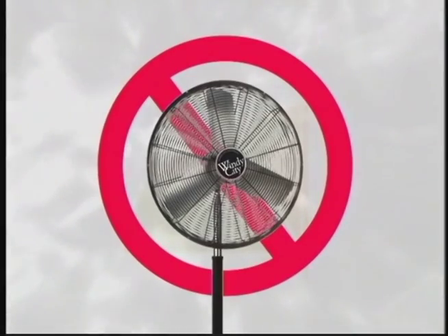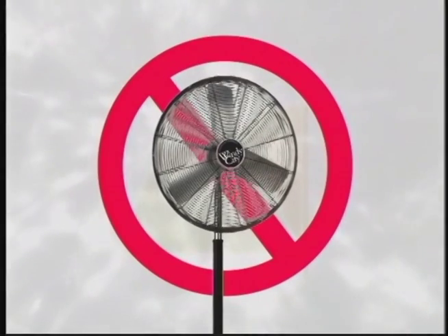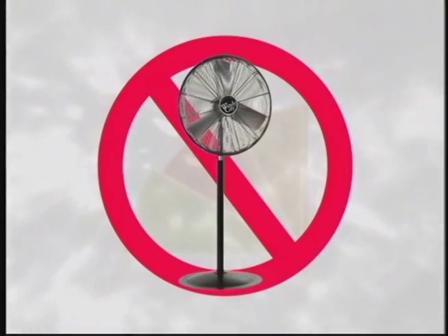Keep air movement and fans off until application is complete and the product is beginning to set. Drying the product too quickly will make it difficult to maintain a wet edge and could prevent deep penetration.